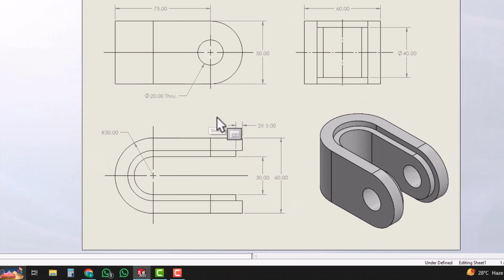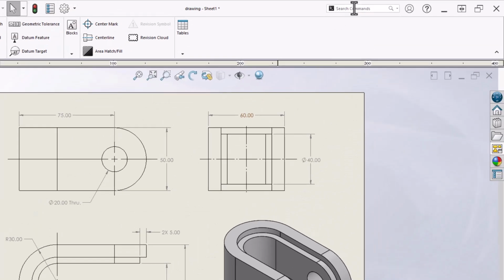If you have been watching this tutorial till now, you are a legend, and legends always get bonuses. So let me give you some bonus tips. Look, you might find the dimensions a little dull, right? So why not make them a bit darker to make them more readable? To do that, go to search and type layer.